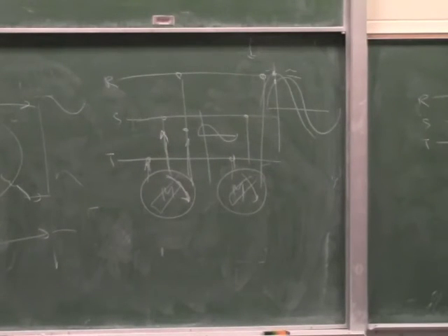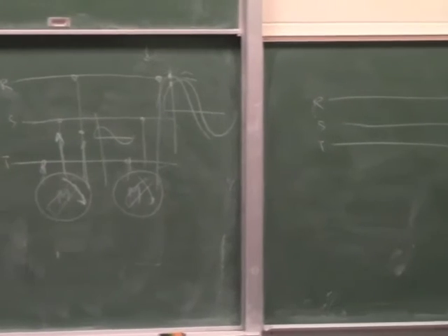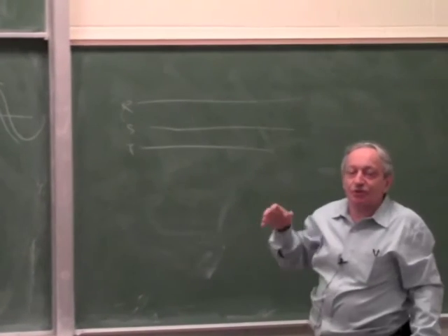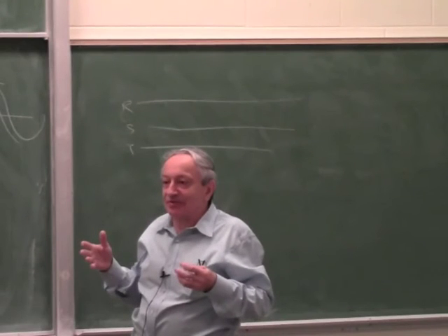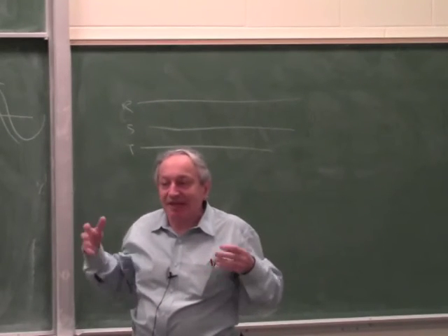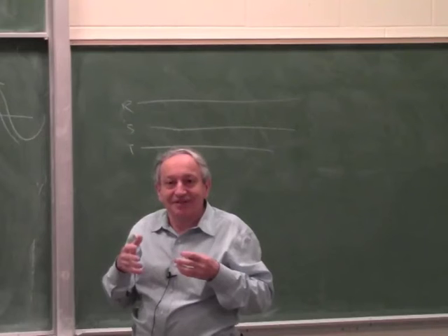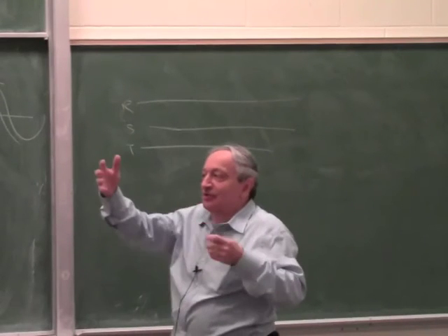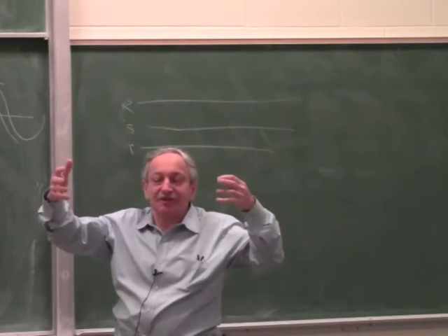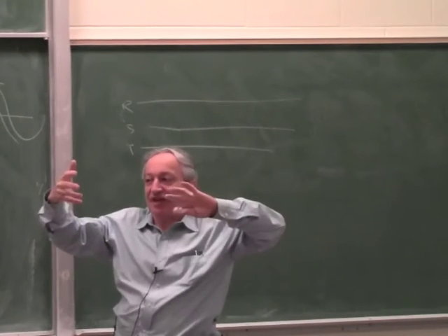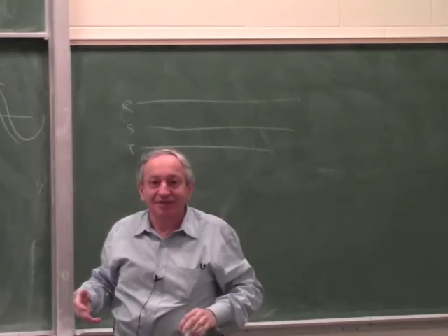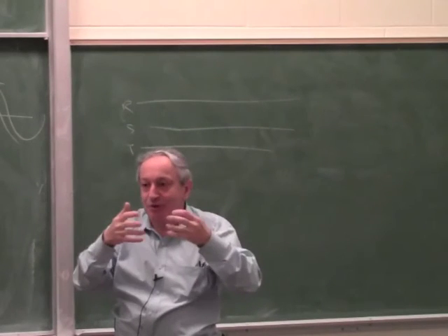These three wires are running all across the country, and there are many power stations which share the load. So how can many power stations share the load of a grid? They have to be linked in phase. Right? Because you can't just connect three-phase from one power station to three-phase of another power station, even if they're the same frequency. If there's the wrong phase, it will be a short. Even if there's a phase difference, there will be a short.